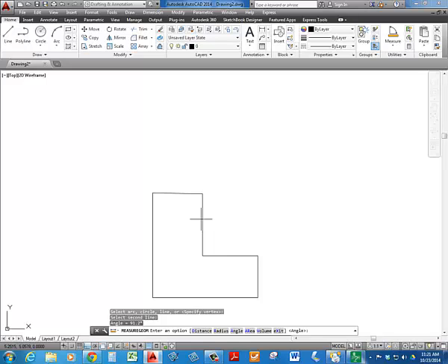Again, AutoCAD is very unforgiving. It wants everything connected. It wants perfect angles. It wants all of that to work efficiently and accurately for you. So 91.2 is the actual angle. So as you're drawing, and heck, even after you finish drawing, you think it looks perfect, it wouldn't hurt a thing to kind of click on 2 or 3 entities and measure them.